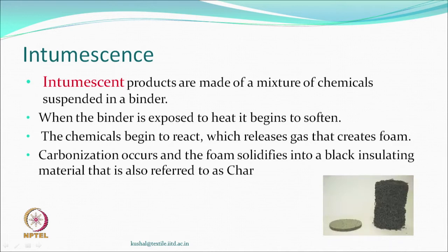You may have seen some products like a tablet of an intumescent mixture, which may be solid, and the moment you put a certain amount of fire to this, it will start burning because the polymer is there. There are products inside which will start burning, and suddenly a large volume would be created, which basically is char, a black, very soft material that remains, but the volume obviously is increased because foaming is taking place.